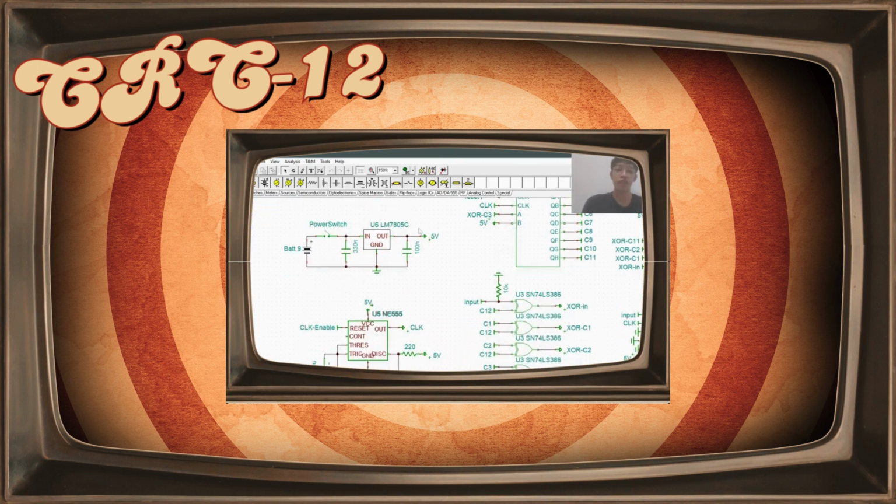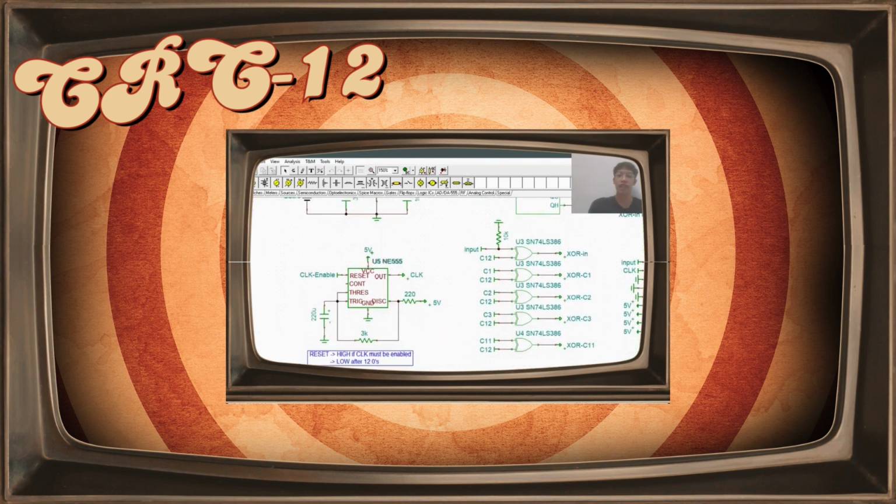Then here we have this LM7805 IC, which is a 5 volt regulator. This 5 volt regulator is crucial in our circuit since, based on their datasheets, the majority of our ICs have a maximum supply voltage of only around 6 volts. Using the 9 volt battery we have as our supply voltage will damage them. So it is essential to step down our supply voltage from 9 to around 5 volts to ensure that the ICs will work as intended.